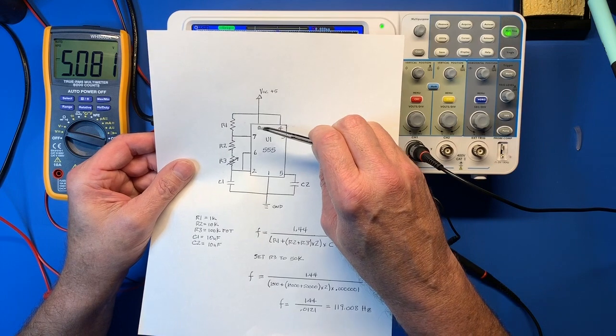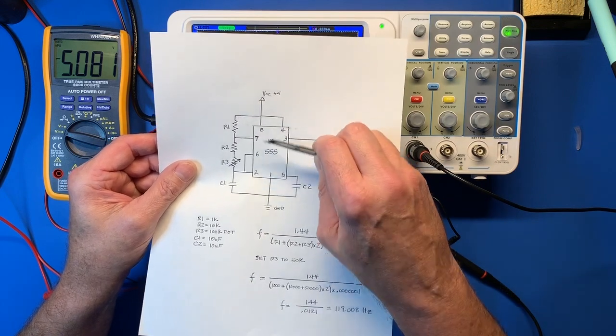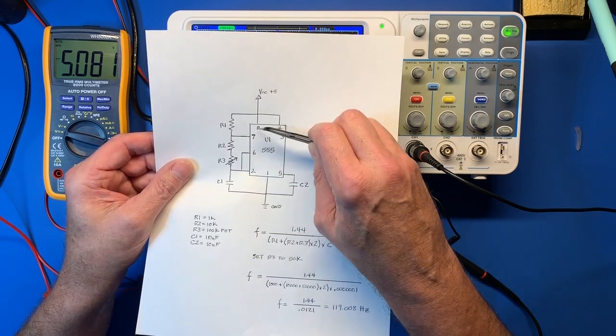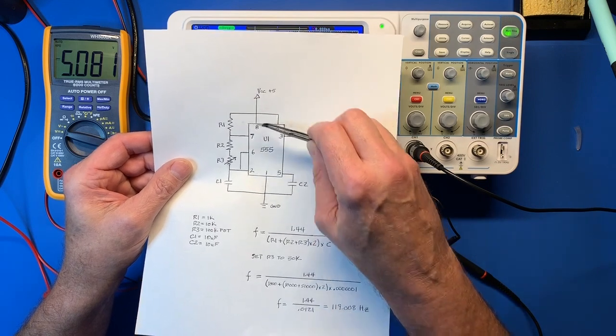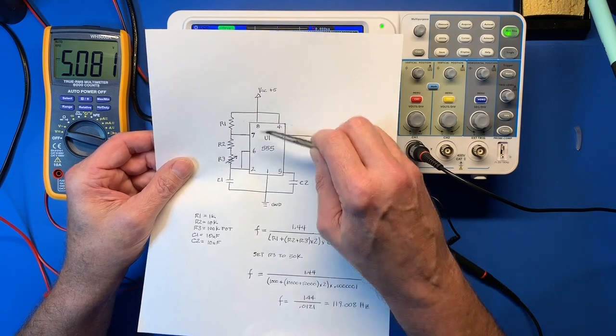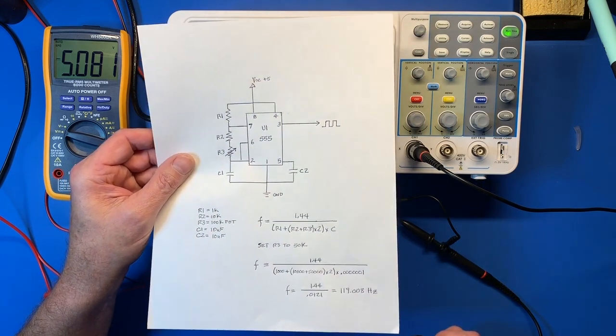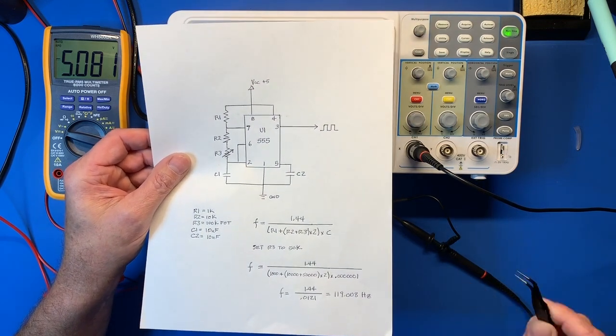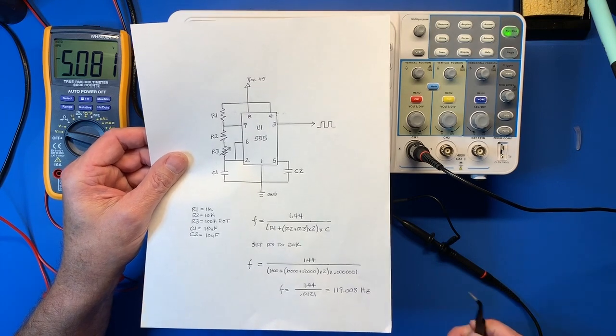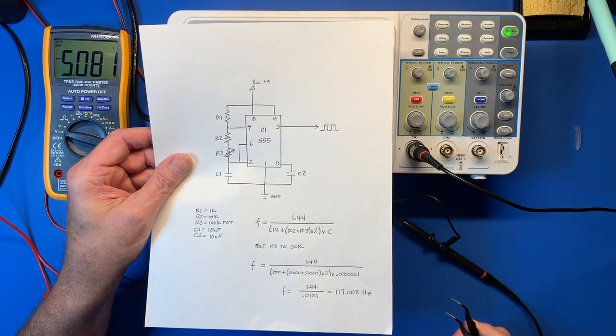So what we often do is put a capacitor between there to stabilize the micro shifts in the signal across the power supply. It's called a decoupling capacitor. It decouples high frequency and those micro shifts, those noise characteristics.